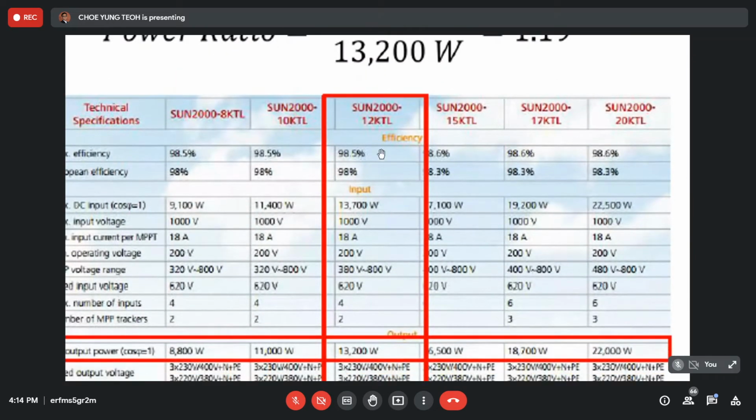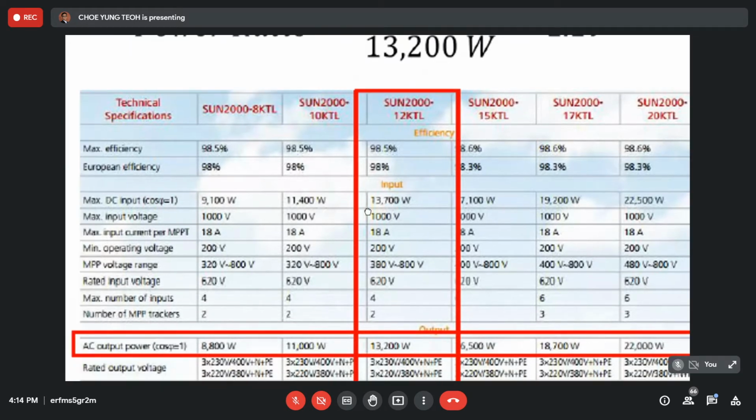So of course, I have to choose the Sun 2012 KTL, which the maximum DC input is 13,700 watt, which is the closest to 12,500. You cannot use 11,400 because it is too low already. If you want to use that, you also can, but you will not fully utilize the power output. We have to take a balance between the module utilization and the inverter utilization.